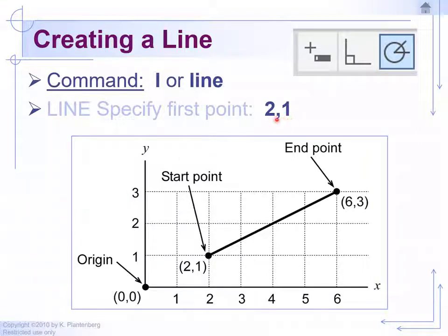Click on it and then you can type in 2, 1. This will be your XY coordinate. It's difficult to see in AutoCAD, but if you look closely, you'll see a red and green line, and that is your X and Y axis, and the intersection point is the origin, which is 0, 0. Okay, so after you click on the line command, you type in 2, 1, and you'll see it in the command line. That'll define our X direction, 2 in the right direction, comma, and then 1 in the vertical.